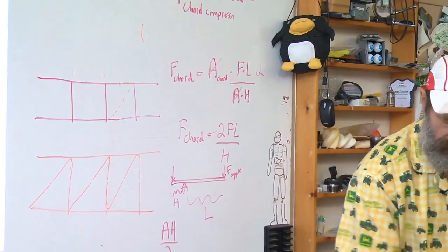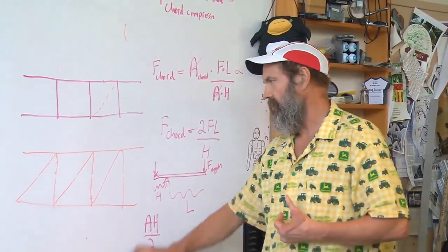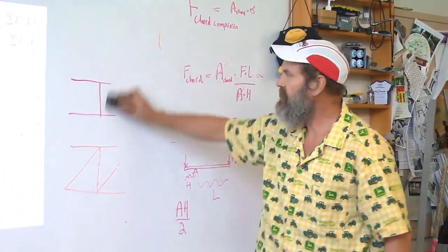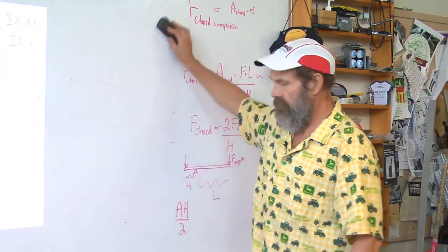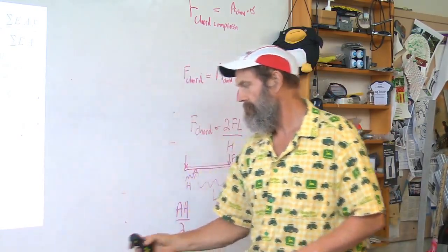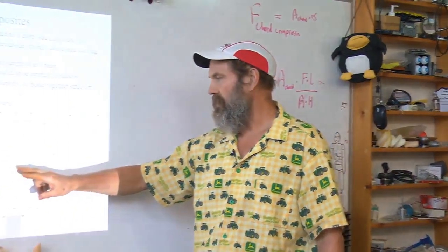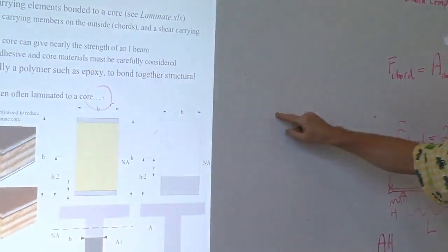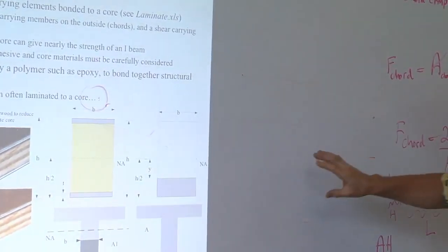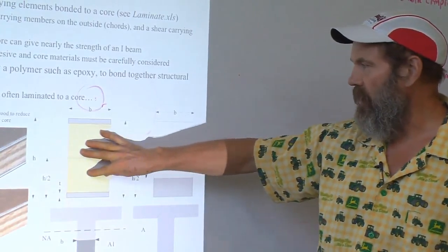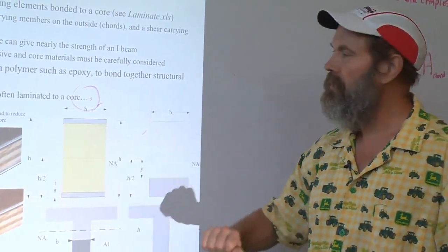It's really important that you develop your own internal feel or experience. Now, from truss, a very similar type of analysis and thinking with respect to the neutral axis and stiffness applies in a composite. Instead of having the bracing, those diagonal members, you'll have a solid, and it may just be foam, it may be honeycomb.